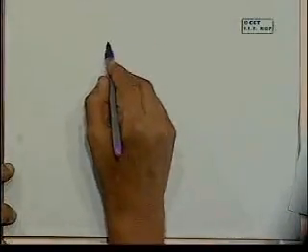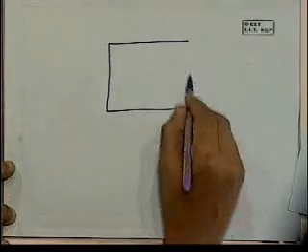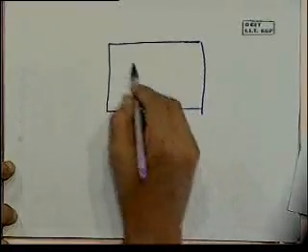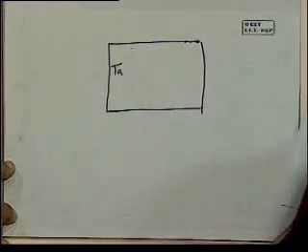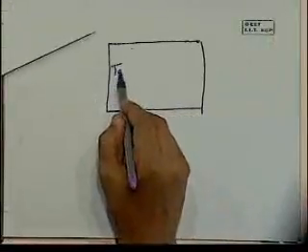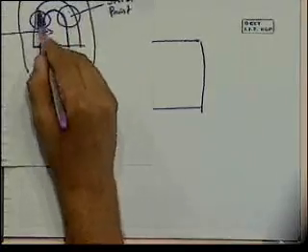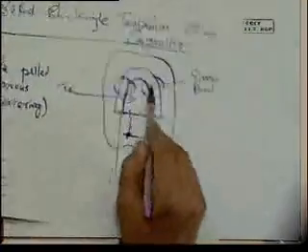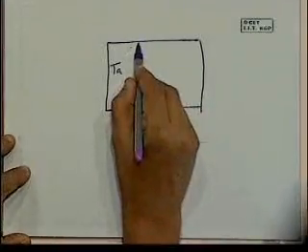When we look at that area, it looks very similar to the case of the liquid electrolyte cell, except that instead of two aluminum foils, what we have now is the tantalum pellet, the inner part of it. Well, what I'm drawing here will be more like this area, this side. So the tantalum is on the inside. It doesn't matter one way or the other. I'll just have to reverse the diagram.